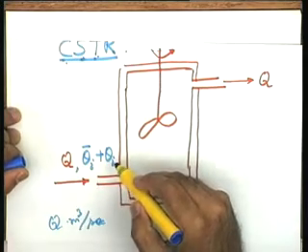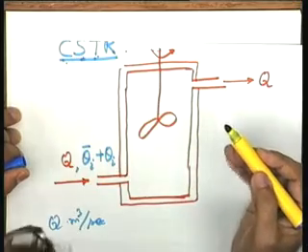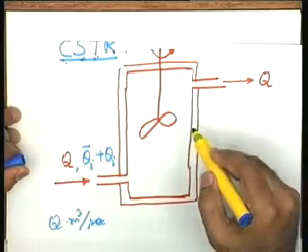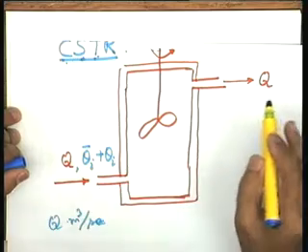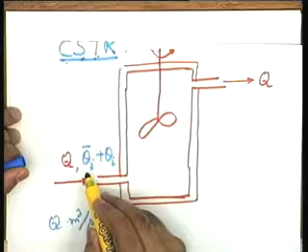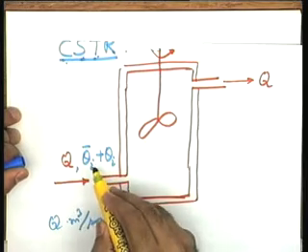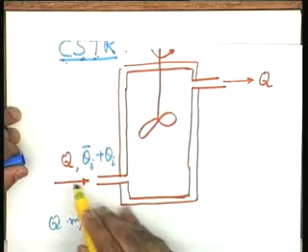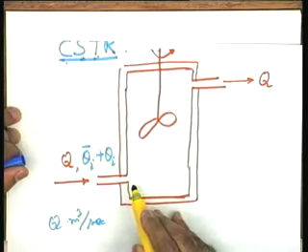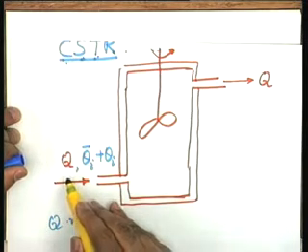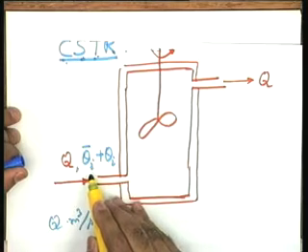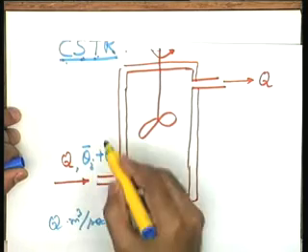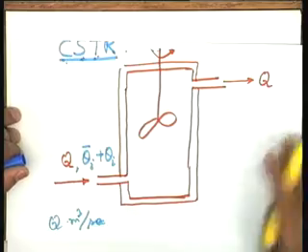It is a perturbation in the system, maybe an uncontrolled perturbation, and you want to study the effect of this perturbation on the dynamics of the system. This will become my standard symbol, that is I will be representing a steady state and a perturbation. Steady state corresponds to nominal operation of the system. Okay? So, I assume that the input conditions correspond to Q, a constant flow rate, and a temperature theta I bar plus theta I, the units being degrees centigrade.